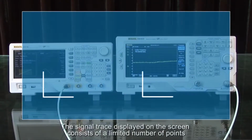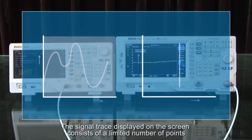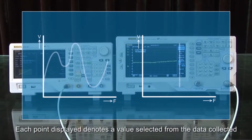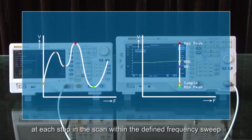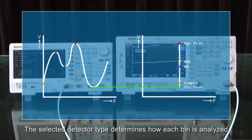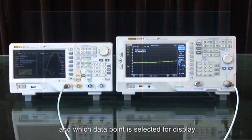The signal trace displayed on the screen consists of a limited number of points. Each step in a frequency scan collects a bin of data. Each point displayed denotes a value selected from the data collection at each step in the scan within the defined frequency sweep. The selected detector type determines how each bin is analyzed and which data point is selected for display.